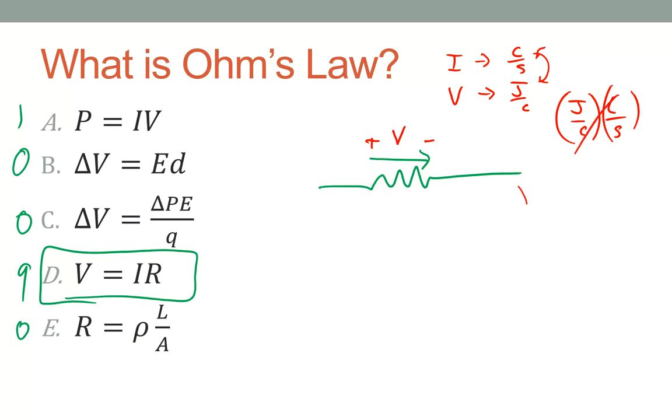And that's power. Now, a resistor always absorbs power. A resistor is never supplying you power. So if you have the current and the plus and minus the way it is for a resistor, that's the configuration that gives you absorbed power. If it goes the other way, that would be supplied power.